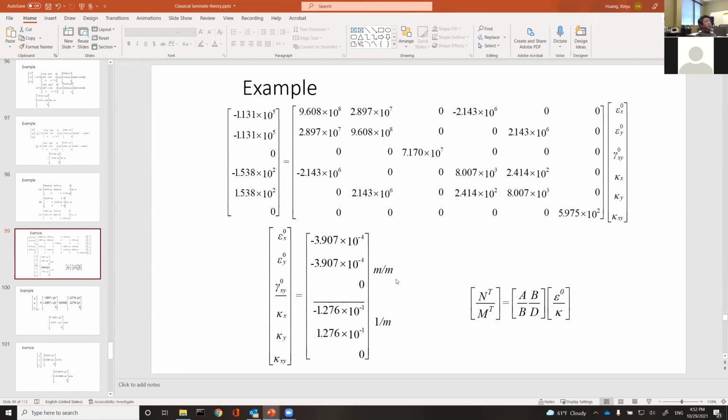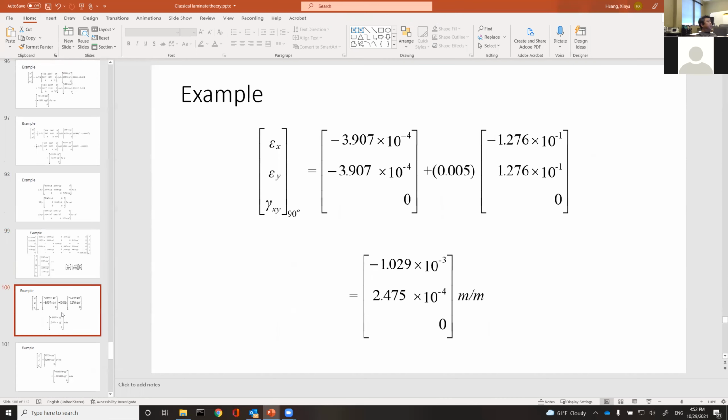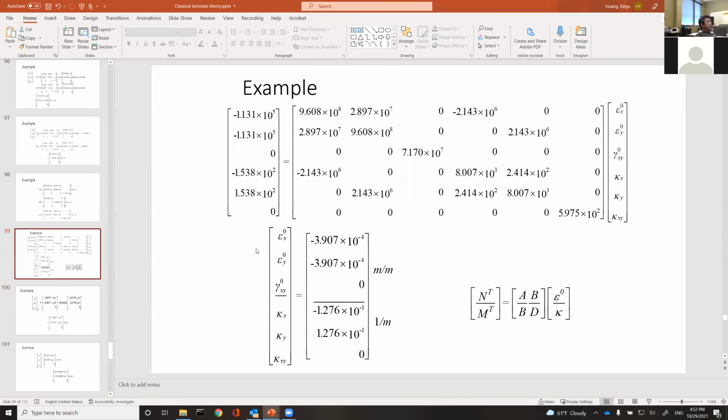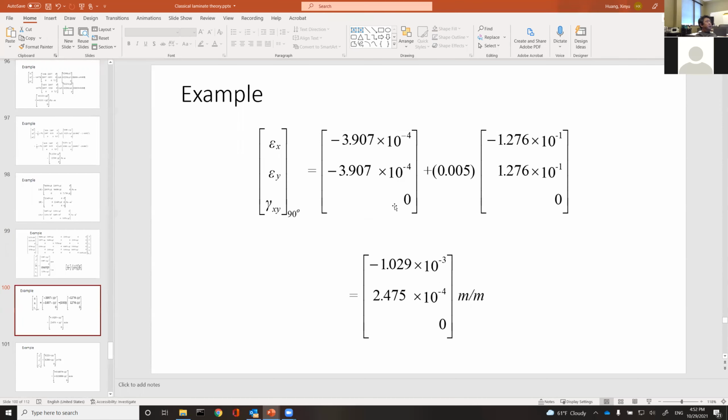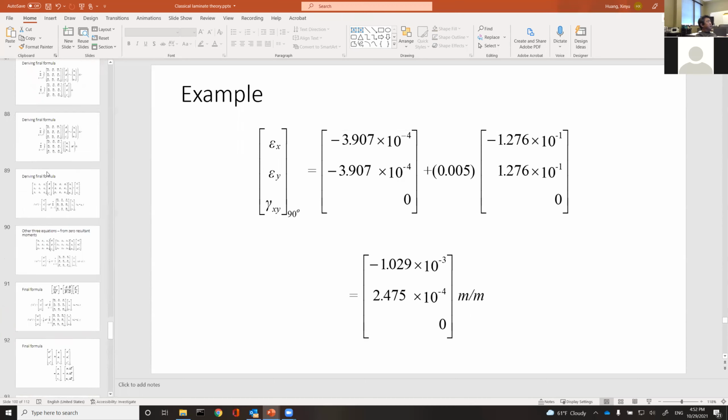And you can also calculate thermally induced stress. You calculate the mechanical stress, and you calculate the total strain in each layer using the Kirchhoff assumption that we learned at the start of CLT. So using this set of numbers, the mid-plane stretching and the curvature, you can calculate total strain anywhere in the laminate. Let's review the Kirchhoff assumption. Kirchhoff assumption is this.